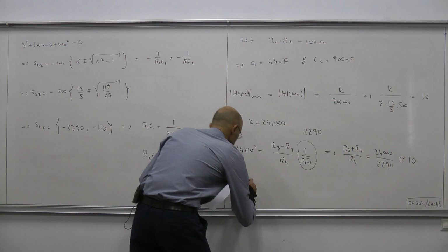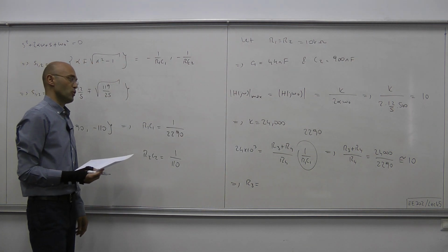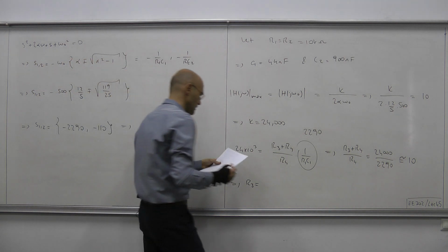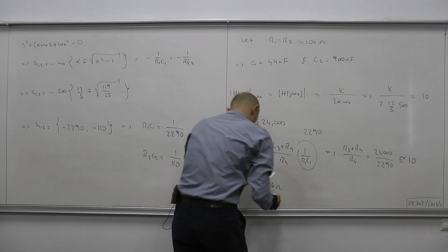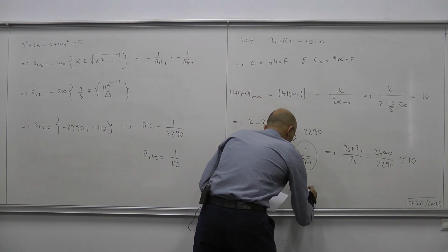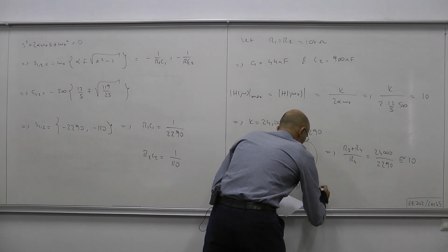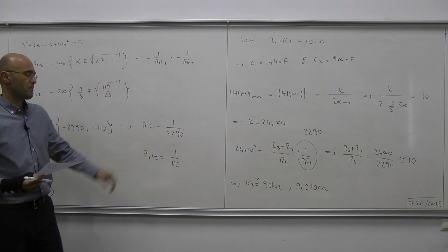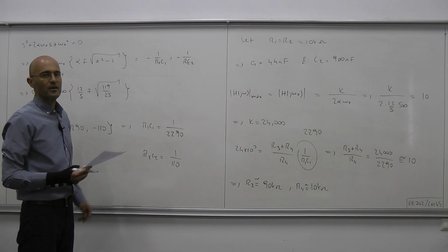We can therefore choose any resistance values with ratio 9, and they should be over 1 kilo ohm. So let's choose R3 as 90 kilo ohms and R4 as 10 kilo ohms. These values should satisfy the design constraints.